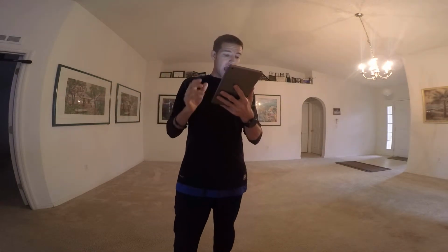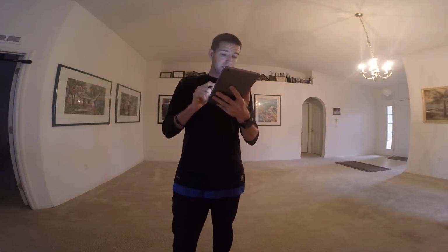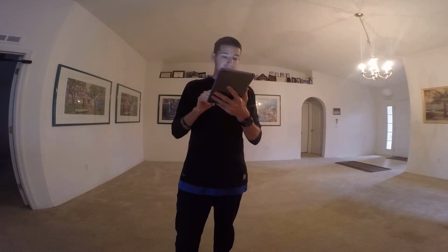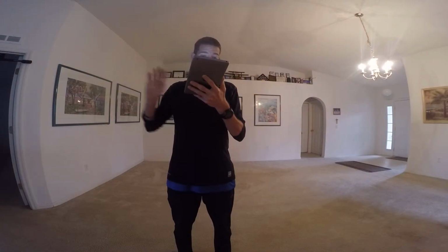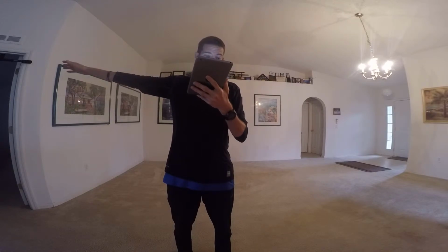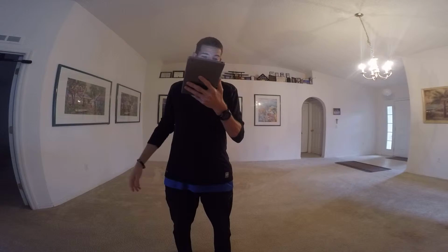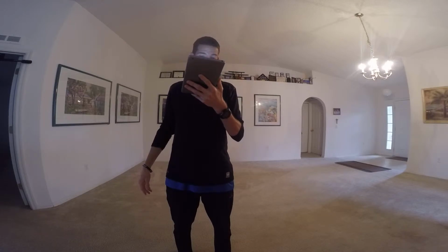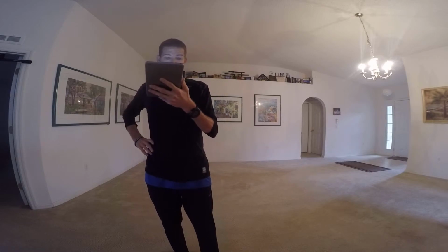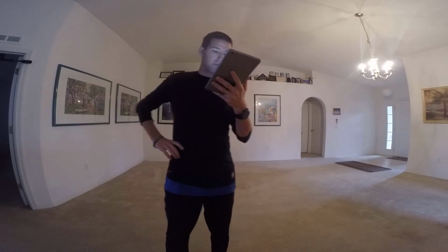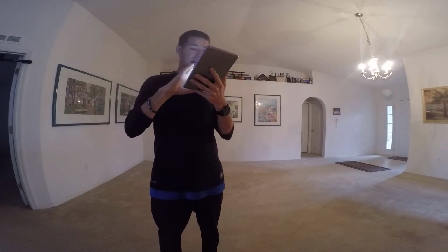Advancing blade. As the relative wind speed of the advancing blade increases, the blade gains lift and begins to flap up. It reaches its maximum upflap velocity at the 3 o'clock position, where the wind velocity is the greatest. This upflap creates a downward flow of air and has the same effect as increasing the induced flow velocity by imposing a downward vertical velocity vector to the relative wind, which decreases the angle of attack.